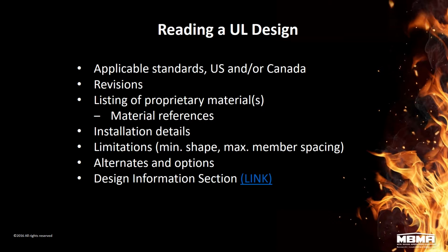So this is a very specific menu of items for each and every rated assembly that must be followed. Any substitutions one must be very careful with, because they may not be correct, and it's always subject to the discretion of the local building official. In certain cases, an independent engineering judgment evaluation may be necessary to approve a substitution.